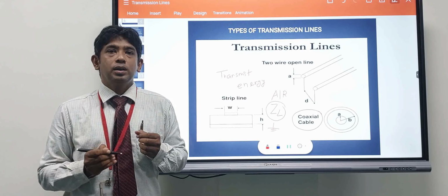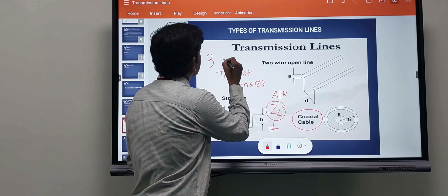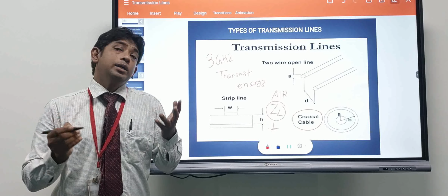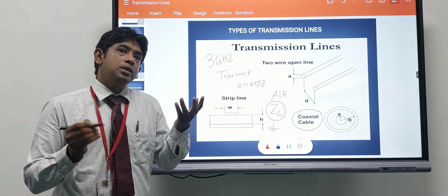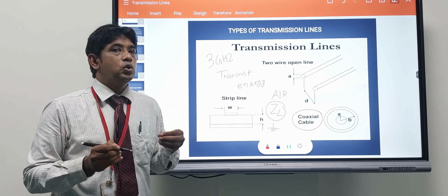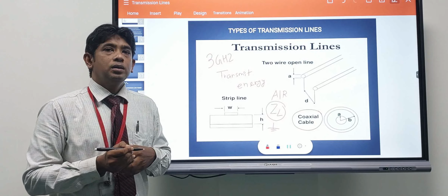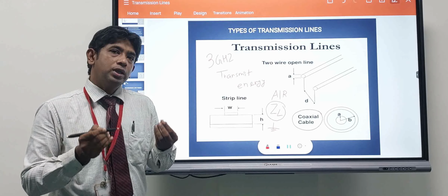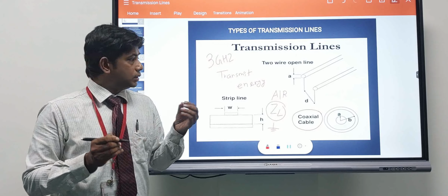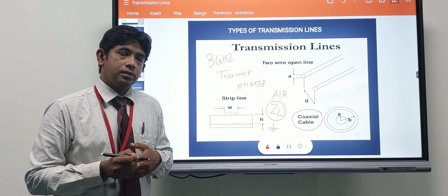The coaxial cable can be used up to 3 GHz and therefore transmits large signal powers. Beyond this frequency, the transmission of electromagnetic waves along the coax becomes difficult. In the solid medium, it needs support for the conductors and there are corresponding losses. This is also associated with a phenomenon called skin effect.